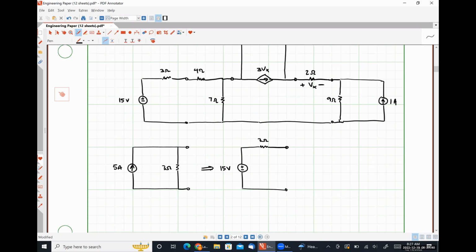One thing that isn't super obvious here is that now that 3 ohm and that 4 ohm resistor can be combined, where previously they could not, okay? So because it changes the position of resistors, it can enable resistor combination techniques to be employed for simplification where they couldn't have otherwise been used.